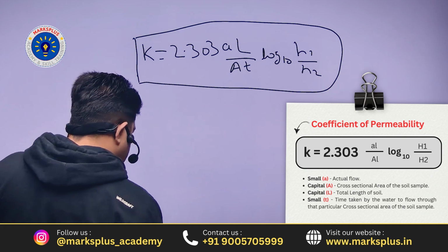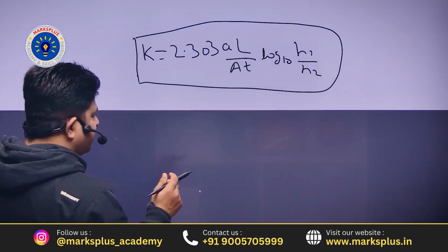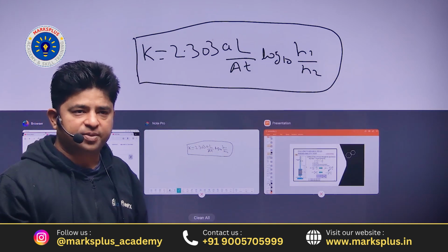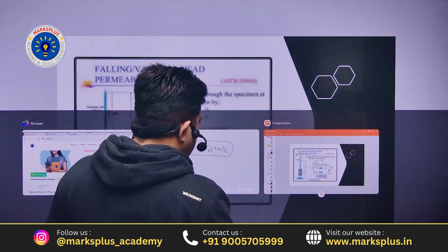Okay. तो दोस्तों इसको आप बेसिकली जो है इस फॉर्मूले को आप रिमेंबर रखिए कि वेरिएबल हेड परमेबिलिटी टेस्ट किस में यूज किया जाता है फॉर द फाइन ग्रेन सॉइल, कांस्टेंट हेड परमेबिलिटी किसके लिए यूज, कौन से सॉइल की टाइप के सॉइल के यूज किया जाता है फॉर द कोर्स ग्रेन सॉइल. ओके.